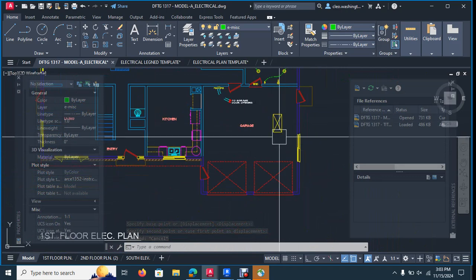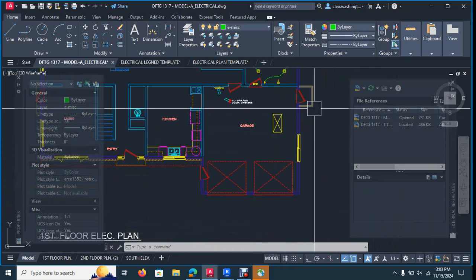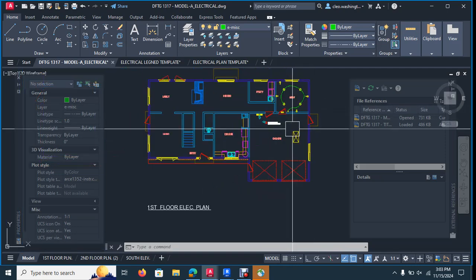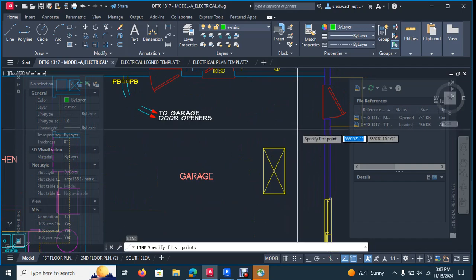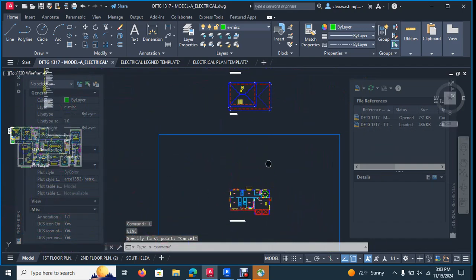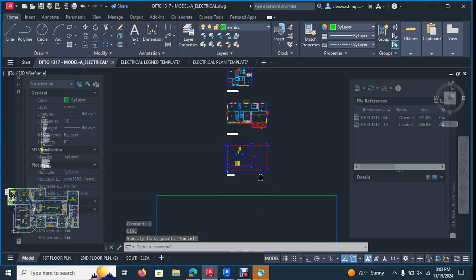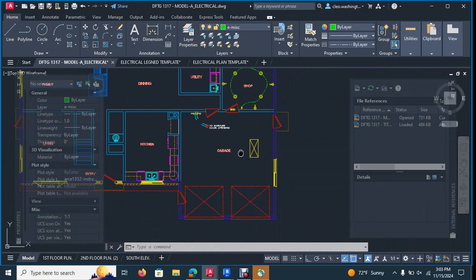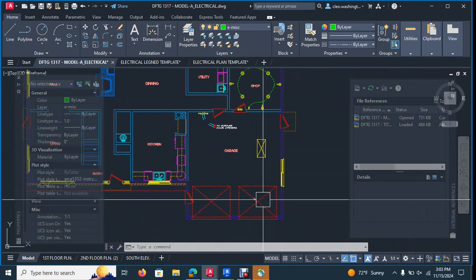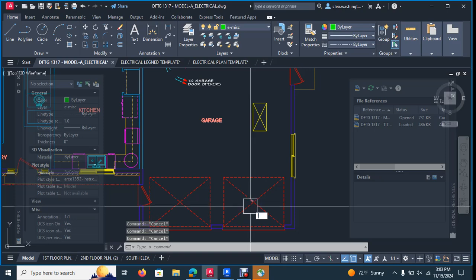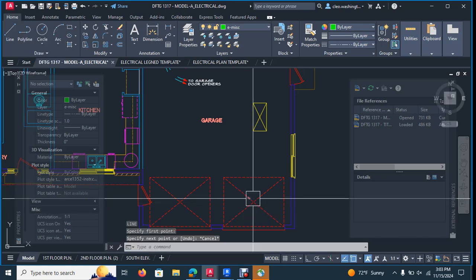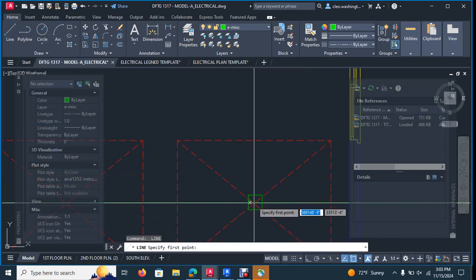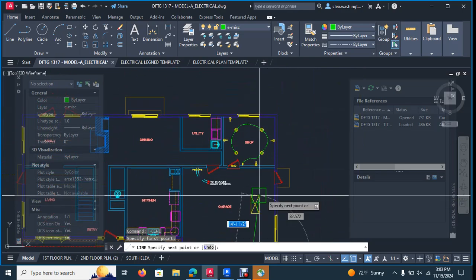I think where we've placed them, we have that 6-inch curb, that 6-inch step up here, and maybe I deleted it. Let's go ahead. It wouldn't show on the RCP anyway. It'll show on the foundation plan, which we have not gotten to just yet. I think the placement of this light is perfect. I would just center it on the garage door. So I would draw a line here from the center of the garage door. Turn your ortho back on.